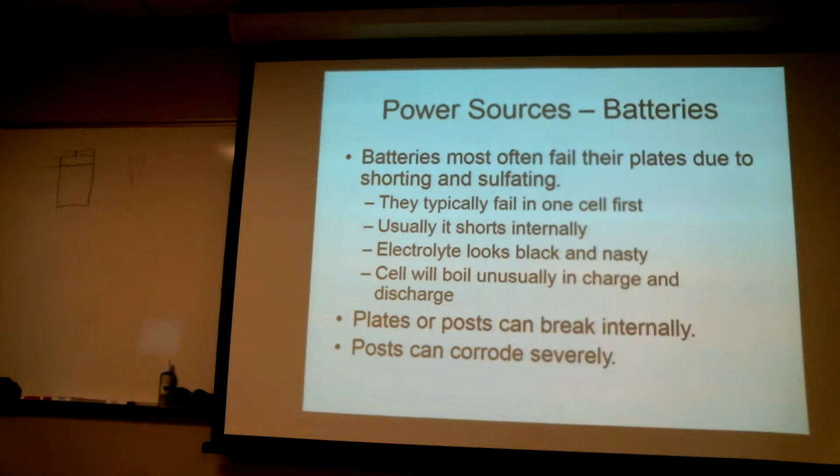If you try to twist it off in a tightened condition, you will fracture. You'll do 2 things. The post coming up out of there, you'll fracture it from the plate, but you'll also delaminate it from the plastic surrounding. So now vapors can wick up around there, and that battery terminal is going to last you a month or 2 before it corrodes off with the acid percolating up through there. So if you deseal the post as it comes through the case, it's going to be a huge problem.